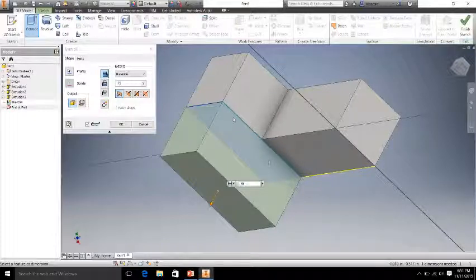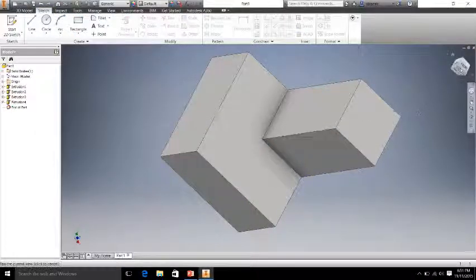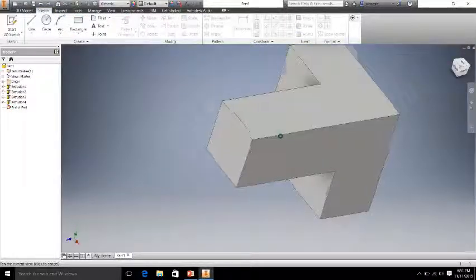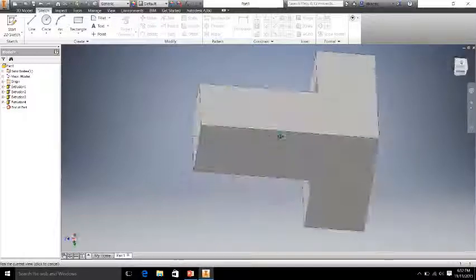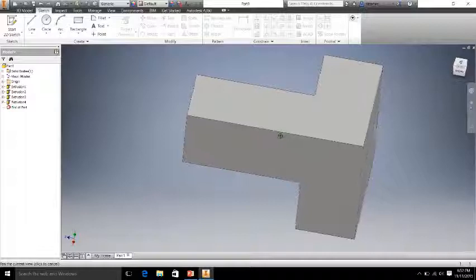And since we selected this whole face, we don't have to judge the distance anymore because it automatically snapped to the 1.5 inches we needed. And so we're just controlling depth at this point. So you can go ahead and hit OK. And look at that. We have the exact green cube that I have created now as a 3D image.